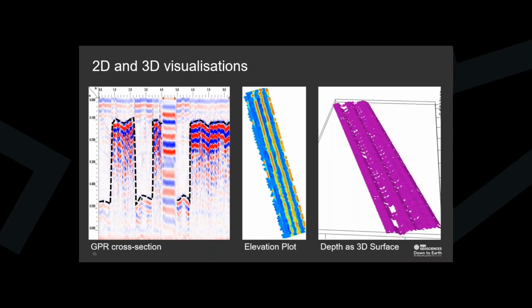So what you can see here is some very localized increases in depth. Essentially that is severe rutting within the asphalt construction of the pavement. In this particular example, the road was not designed for HGV use, but due to changes to the local network, it ended up carrying a lot of HGV traffic, and it just wasn't up to the task. So it rapidly deteriorated, and you had a lot of very deep, very severe rutting, as you can see there.